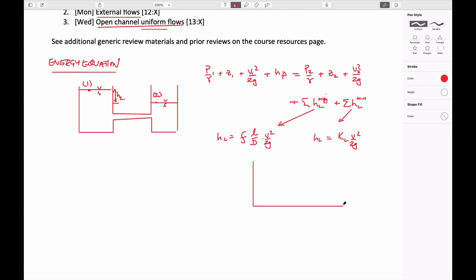In terms of what those represent, we know from the Moody charts that Reynolds number, which is a velocity, a characteristic length, and a density divided by viscosity, where the length is usually a hydraulic diameter, and a Euler number, or a friction factor, or a coefficient of drag, or a coefficient of lift, or a Manning's coefficient are all the terms on the vertical axis, and those are divided between laminar and turbulent behavior